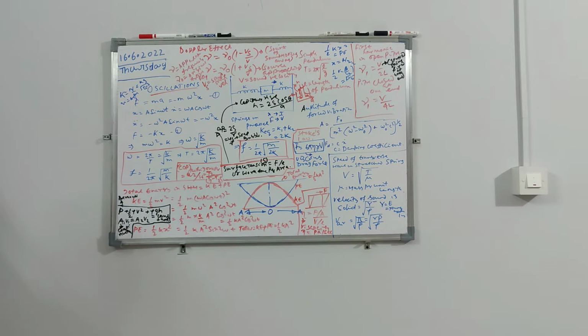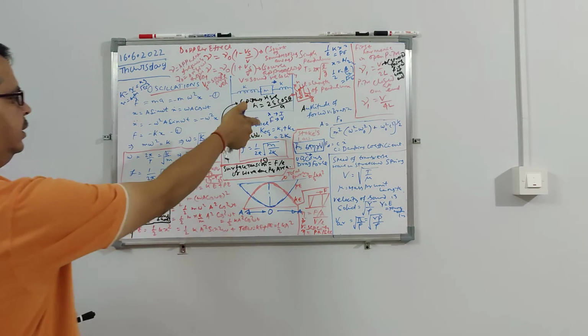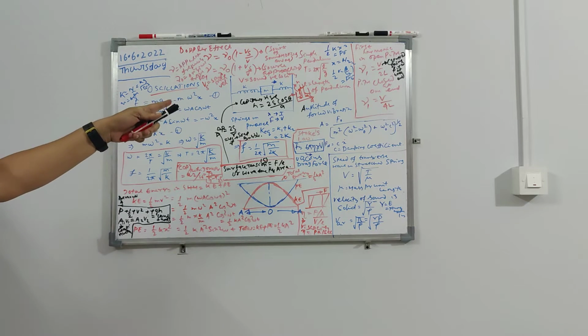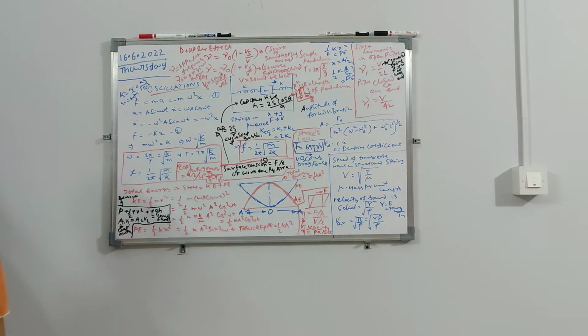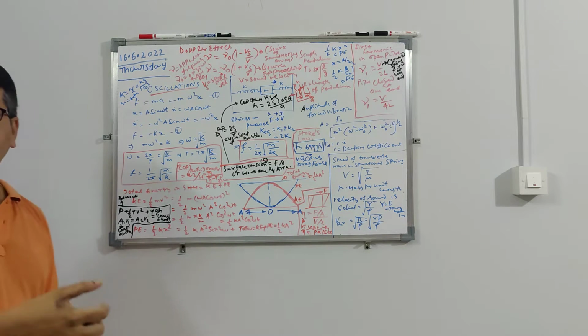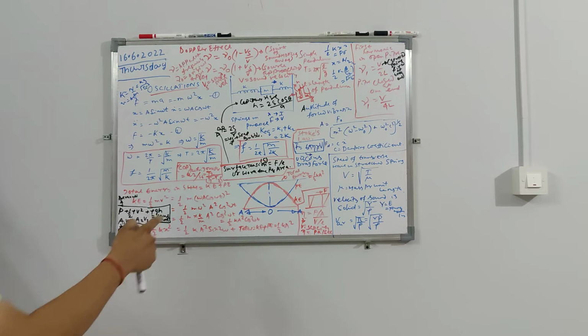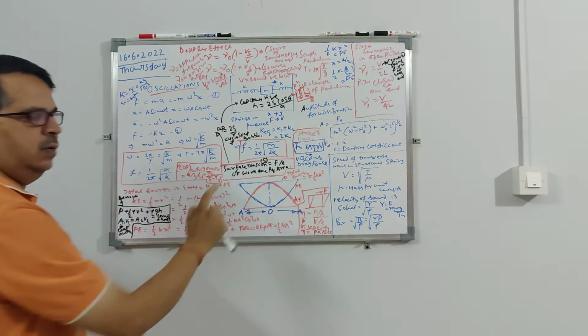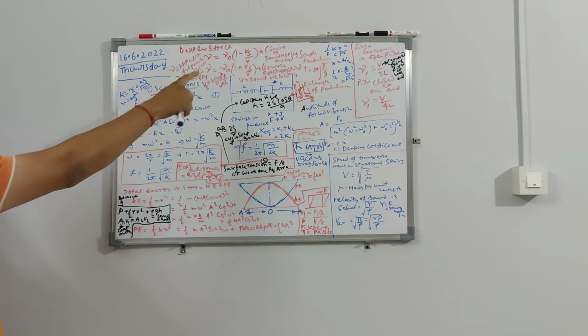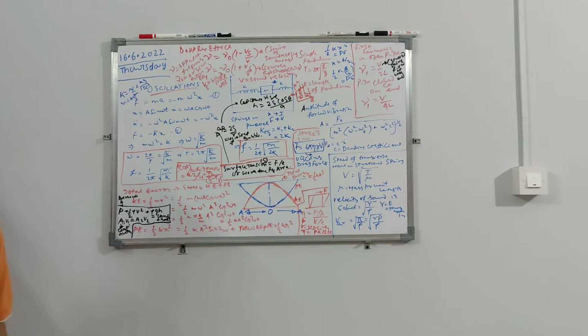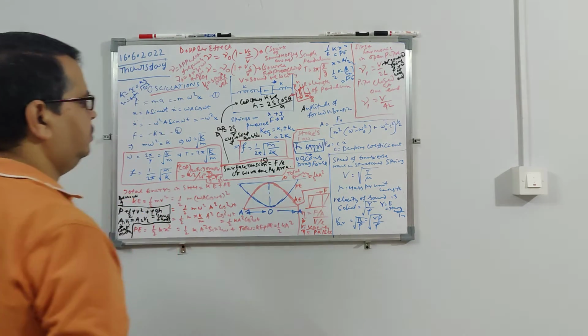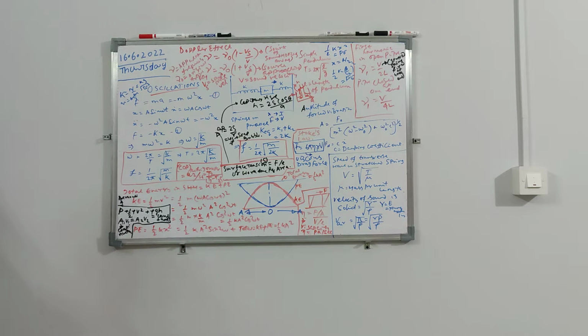Using this principle, if you see a spring mass system like this, the total equivalent stiffness is K1 plus K2, and if both stiffnesses are equal, it will be 2K. So for frequency, K will be replaced by 2K for this system that I am showing. Clear? Now most of the oscillations we have covered. Then, what else is there?